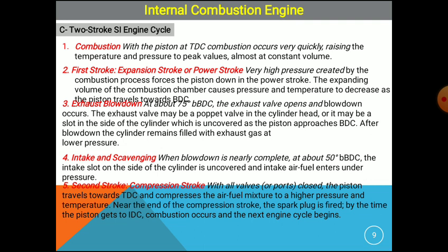The piston travels towards the top dead center and compresses the air-fuel mixture to a high pressure and temperature near the end of the compression stroke. The spark plug fires by the time the piston gets to the TDC. Combustion occurs and the next engine cycle begins.